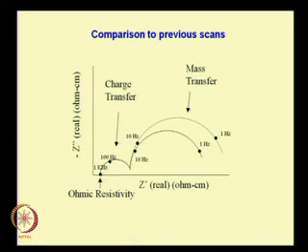In addition, it gives us a lot of insight into how the material is behaving, what is the physics behind the response that we get from the material. If you had done just a DC measurement, you would have just got one value of a very high impedance and another value of a slightly lower impedance or resistance, and you would not have been able to figure out the reason why one is better than the other or one is lower than the other. Therefore AC impedance is a very useful technique.